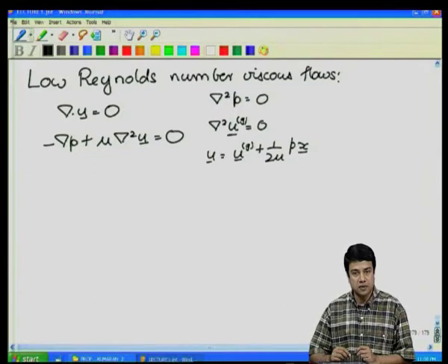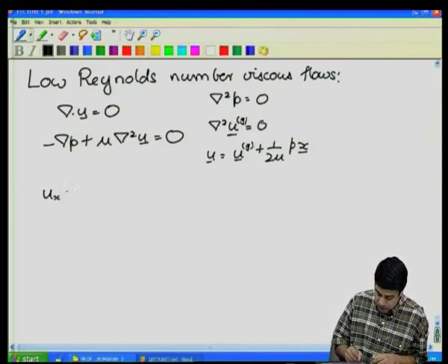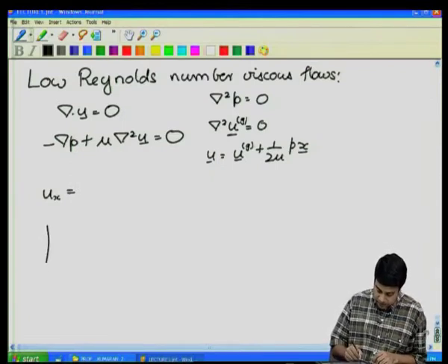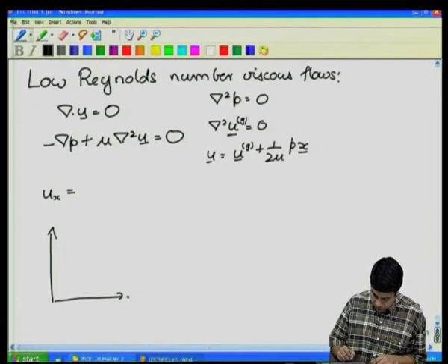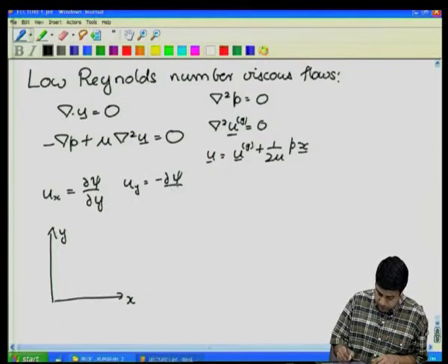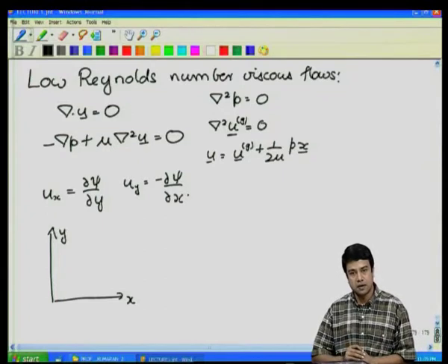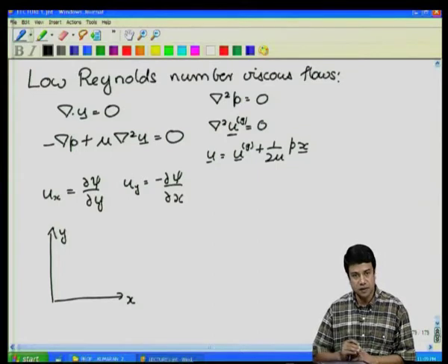We also saw how to reduce the Stokes equations in 2 dimensions to a Bi-Harmonic equation. So, in that case, if you have a 2-dimensional flow in the x y Cartesian coordinate system, you can write u x in terms of the stream function, and the resultant mass conservation equation is trivially satisfied when the velocities are expressed in terms of the stream function.